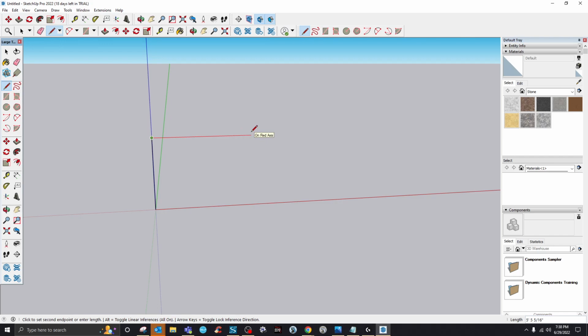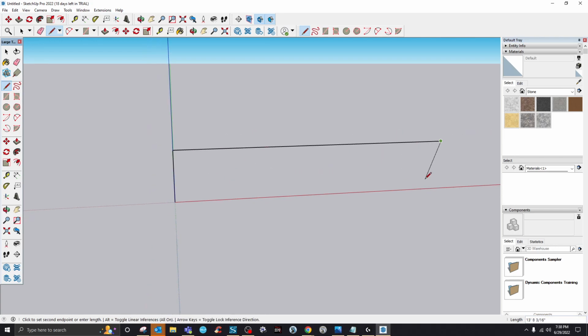The road we want to do is, let's say the 11. You can add a little bit of four for curb and gutter. Let me look at the typical section. Okay, so 22. Yeah, we can do 22 feet. Enter and go down. I mean, it's up to you how to draw it, but basically that's how you're gonna draw it.